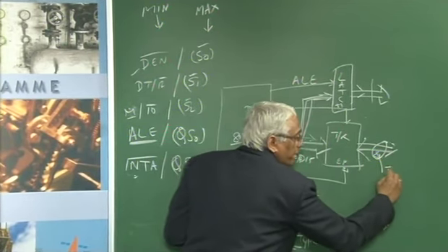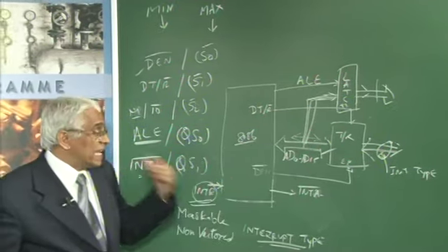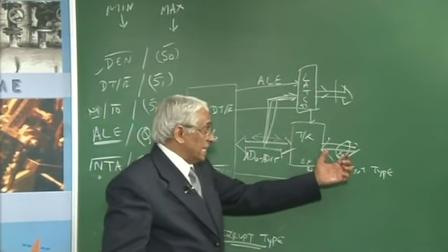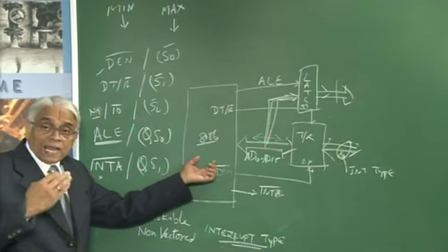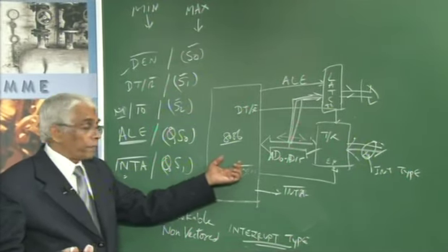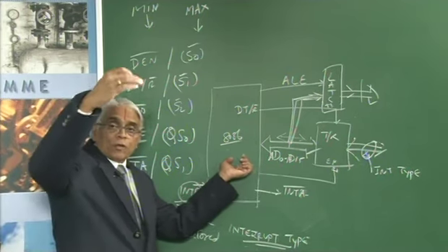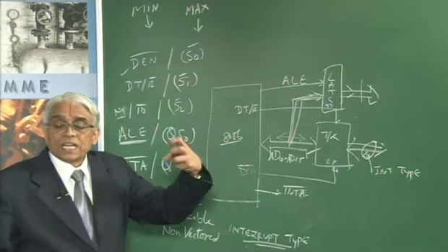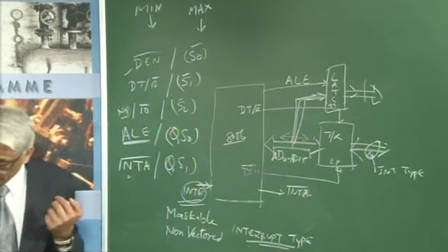The microprocessor takes in this data and calculates the address from where it has to execute the program by multiplying it by 4. It goes to that particular location where the address is given, takes this address, puts it into the registers and starts executing the interrupt service routine.